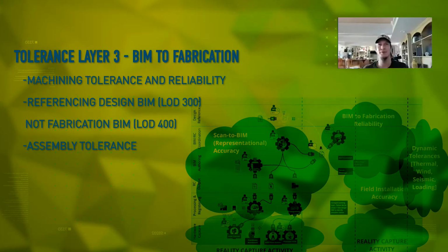And then you've also got how well you're installing it. That really comes down to the accuracy of the control, which can be off substantially, and then the accuracy of the human putting that thing in place. All of those things have variance, right? So if you roll those together, on the fabrication side you're usually talking 1/8 to 1/16 of an inch variation in good cases, up to 1/2 inch in bad cases. When you get out in the field, it's the same thing, probably plus or minus 1/4 inch in good cases, plus or minus 1 inch in bad cases, sometimes even worse.